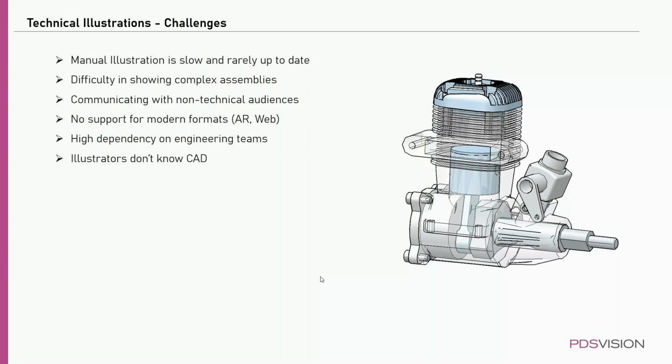Now, when you're publishing these parts, you can have different extensions for publishing. You can have PVZ, which is the Creo View extension, wherein you can open these files in Creo View, which again is free. Creo View Lite is free for your Windchill customers, and Creo View also comes as a free application when you purchase Creo Parametric. So you can open these files in those applications without needing additional licenses.